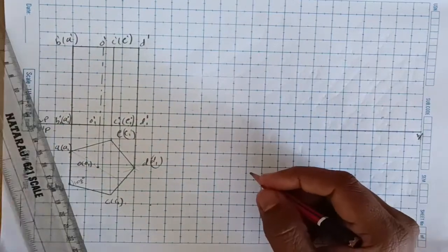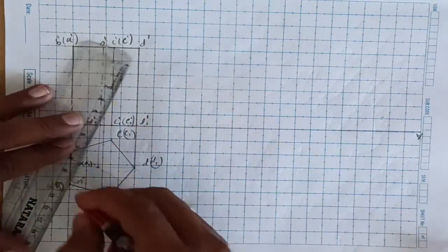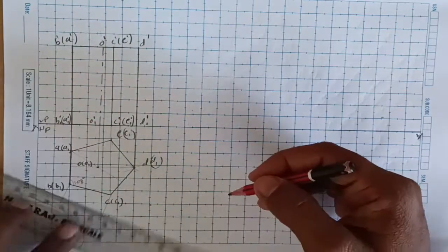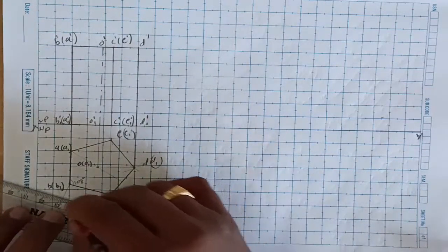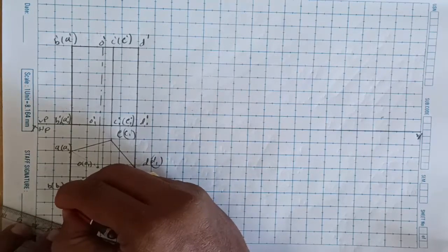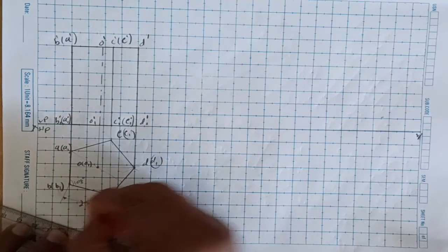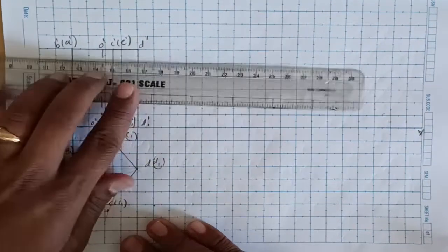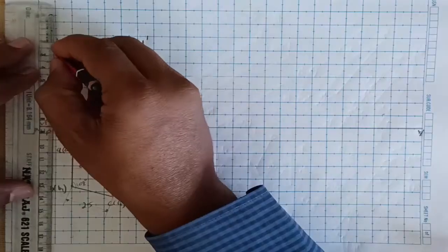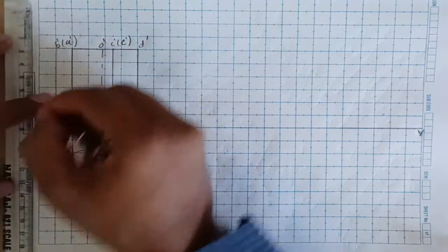Like this we need to do the naming, and you can show the dimensions on any one side. This is the 25 they gave, so we need to draw the extension lines, dimension line and arrow heads, and you can finish this one. Then the axis height they gave is 60. You can show that height here. The axis height will be 60.